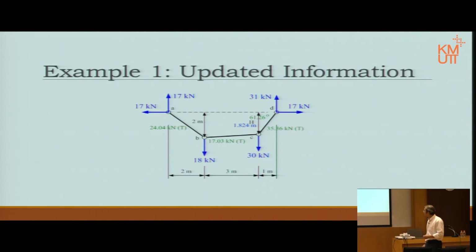One thing though I will mention here, if you notice, every time we take the force component in the cable into the horizontal line, in this case we call X usually, it always comes to the same number, which is in this case 17 kilonewton. And in all other examples of this type of calculation, it will always come down to one number, maybe not 17. It's just a number per application. Okay. Now we're going to look at another example.